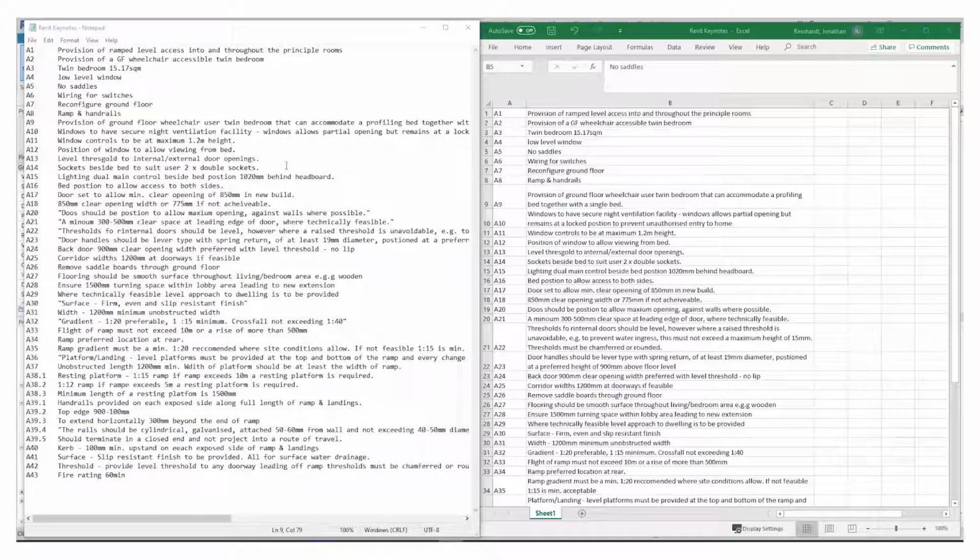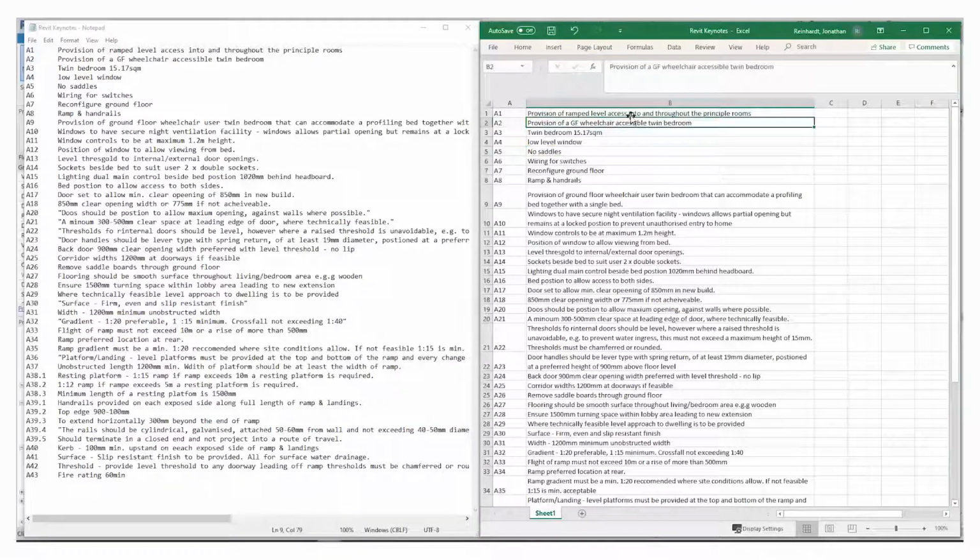Revit's format for receiving Keynote files is a TXT file. So if you create it in an Excel file, it will need to be saved as or exported to a TXT file. These are both the same list. The one on the left has just been saved as a TXT file. These are all specification notes that were custom captured on a particular project, and they've all been given a number on the left-hand side. So you can custom number these if you want.